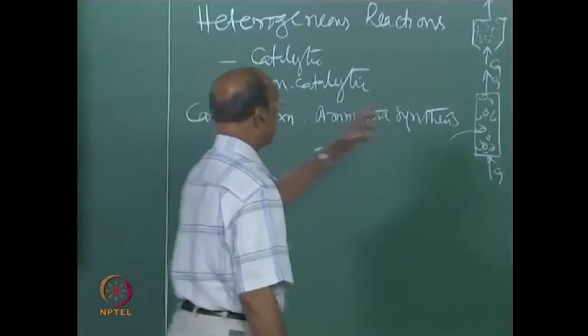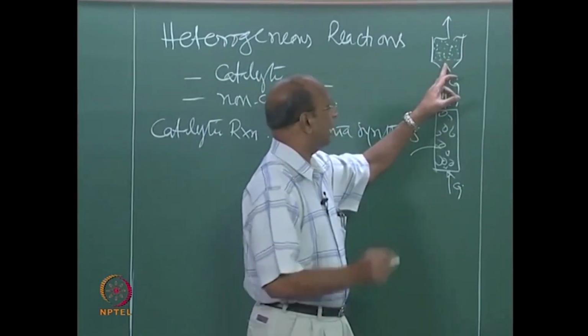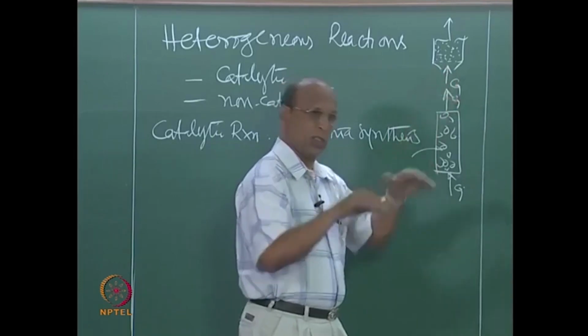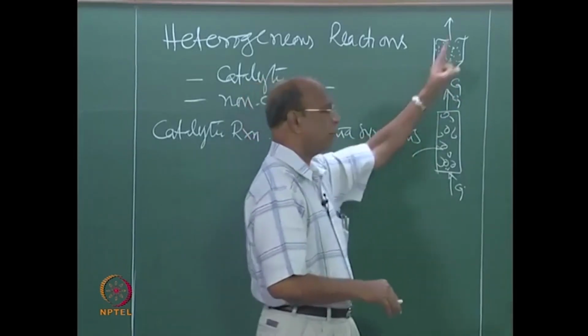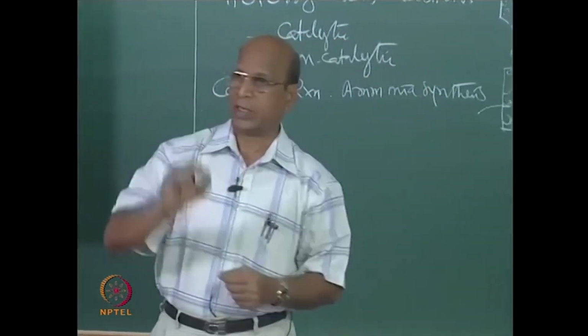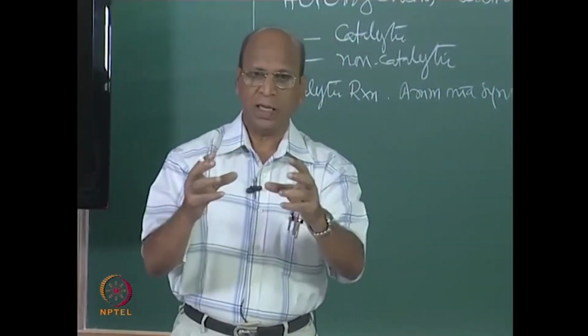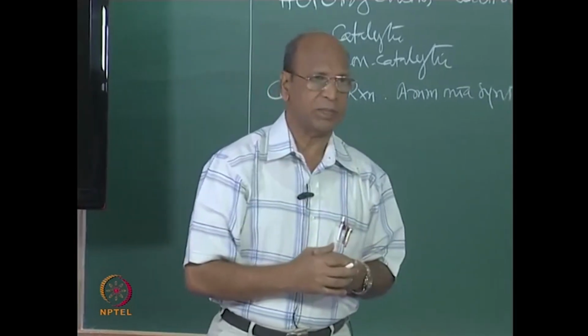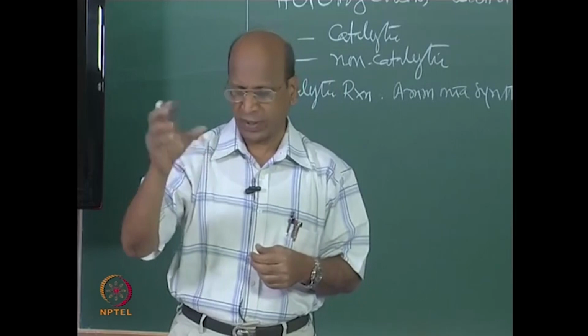Then slowly introduce the air. At very low velocities, the gas will go through the perforations and also between the particles, not inside the particle, but around the particle. In a packed bed we have what is called the void fraction, or porosity, of the bed.